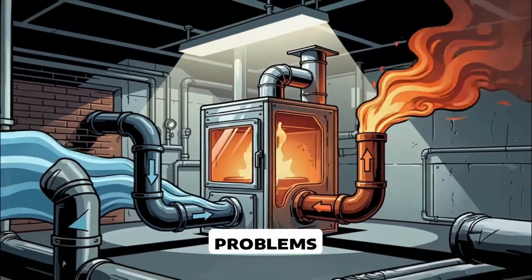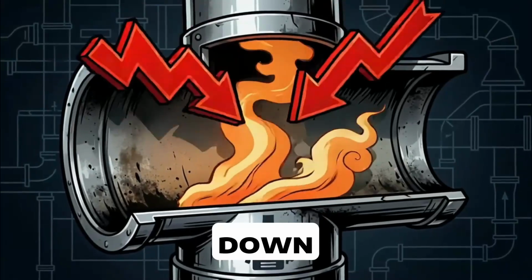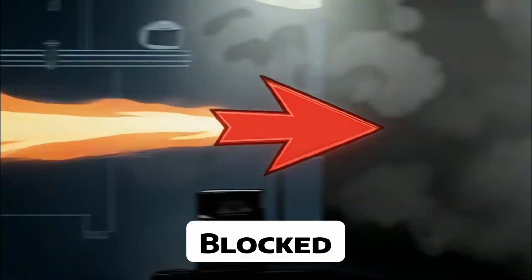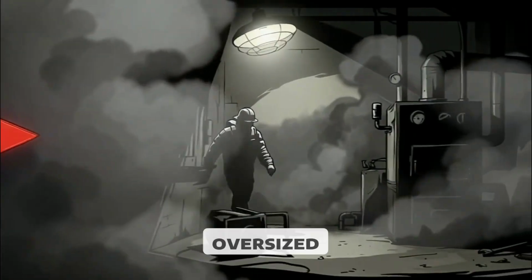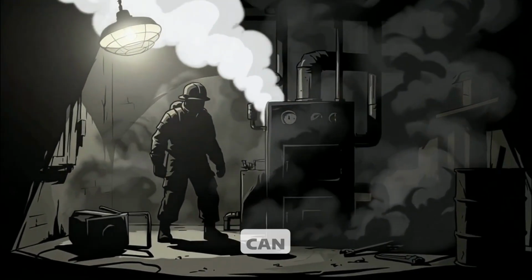Now, draft problems. Downdraft means wind pushes gases back down the vent. Spillage means flue gases spill into the room. Blocked vents, poor draft, oversized chimneys, undersized vents, or negative pressure buildings can all create dangerous conditions.